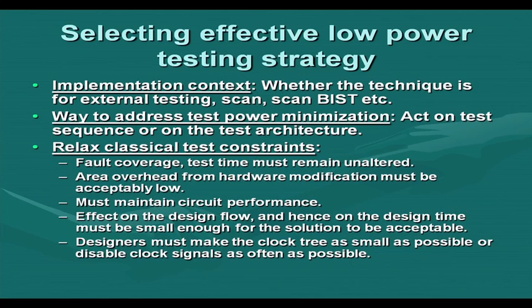And designers must make the clock tree as small as possible or disable clock signals as often as possible. This is another desired requirement from the test engineer's viewpoint. If the clock tree is small, then clock skew will not occur, so delay test and all that can be done properly, and power consumption will also be low due to the clock tree.